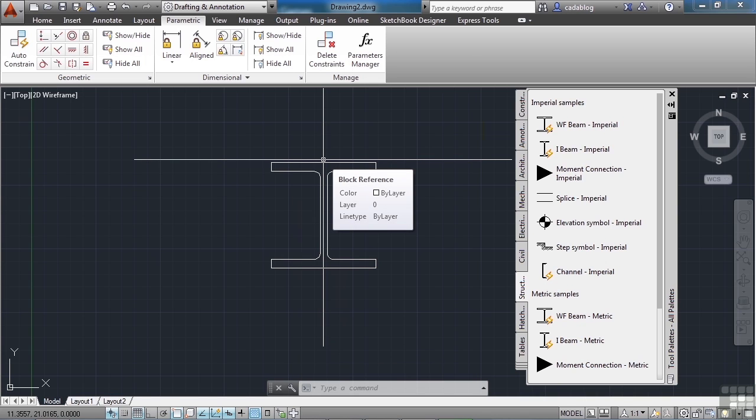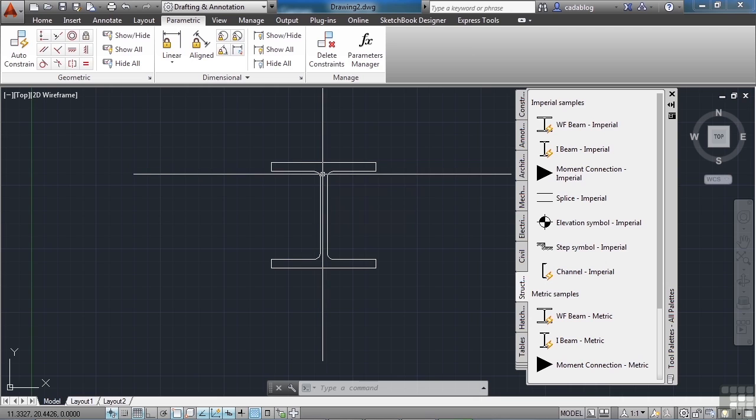One of the problems with constraining your design file is that there's a lot of stuff in it. And the more constraints you add to it, the more difficult it can be, meaning that it can be difficult to work with and difficult to use. Now you have the little things here and there in AutoCAD that say, hey, look, you're going to over constrain this, or hey, you can't move this object the way you want to. Can we relax these constraints for you? You can do that, but after a while, it gets really hard to work with. That's because your file gets larger and larger and bigger and bigger. It's infinite in size, potentially.